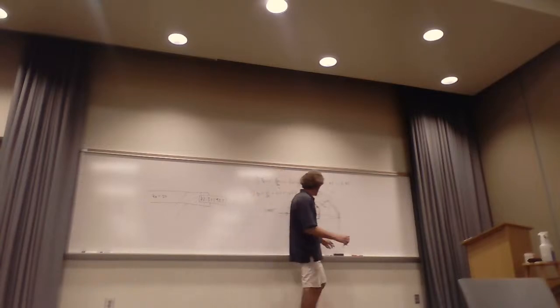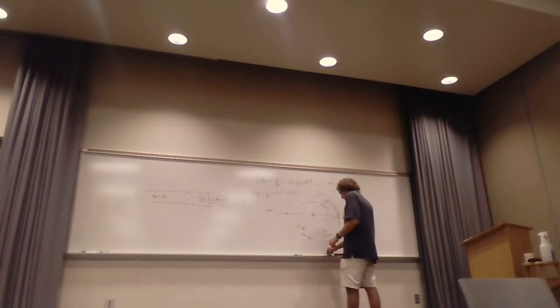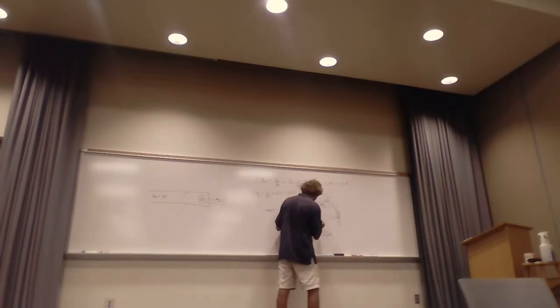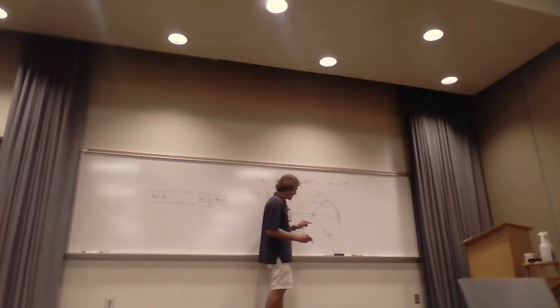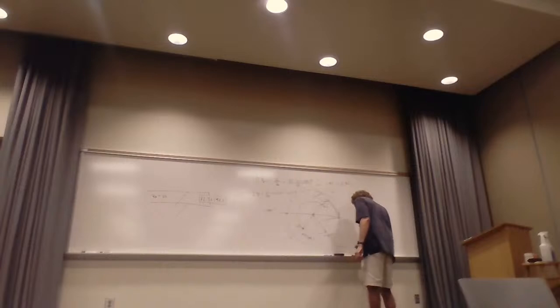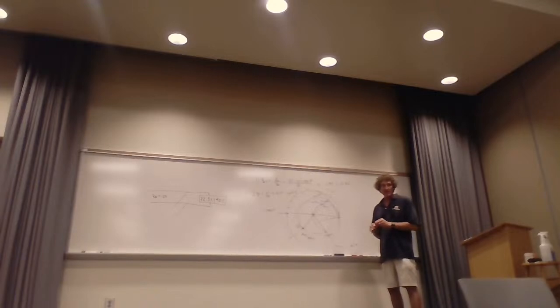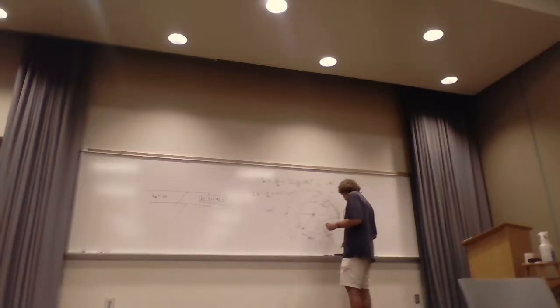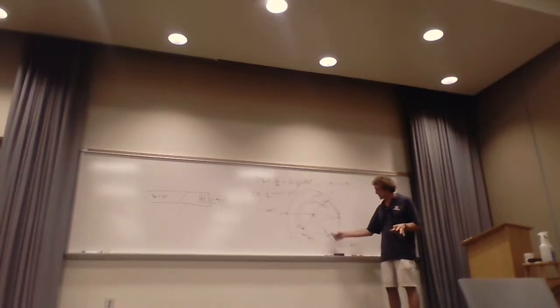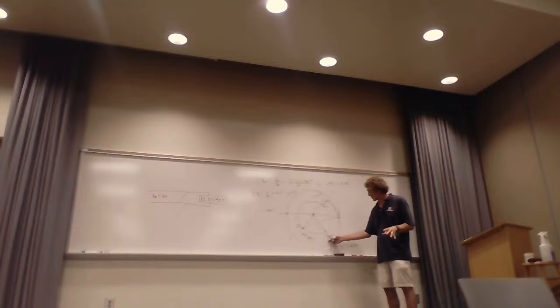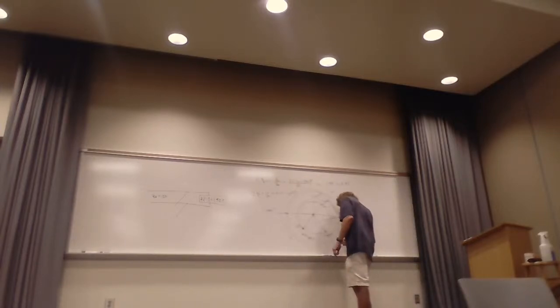Okay, let me just make sure everybody follows what you're saying. What he's saying is if you shoot a line down here, there's a mile marker out here. And I recommend you look at the wavelengths toward generator, the outer circle. Right, on the outer circle, what do you get as the wave number there? 0.345. Is that what you guys got? Not stub length. I want to know what this point is. If you take the line straight from the origin through the point 1 minus j0.8, where do you hit? 0.345? Okay.